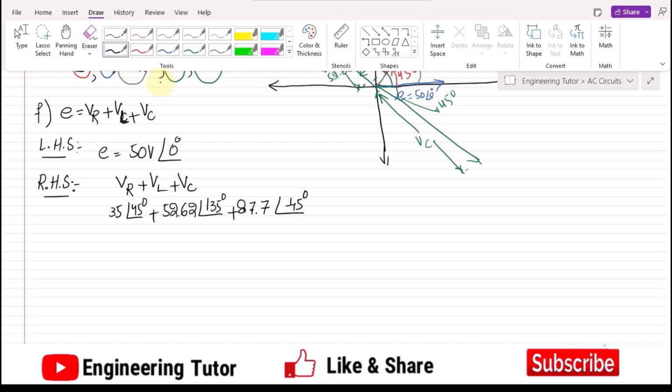Now in order to solve it manually, what we can do is that these are all quantities in the polar form, and we have seen in our phasor videos that in order to add the phasors, it is convenient to convert them into the rectangular form first, then add all the real quantities and the imaginary quantities, and after calculating the resultant in the rectangular form, we have to convert it back into the phasor form. Okay, so that is a feasible method if you are doing it manually.